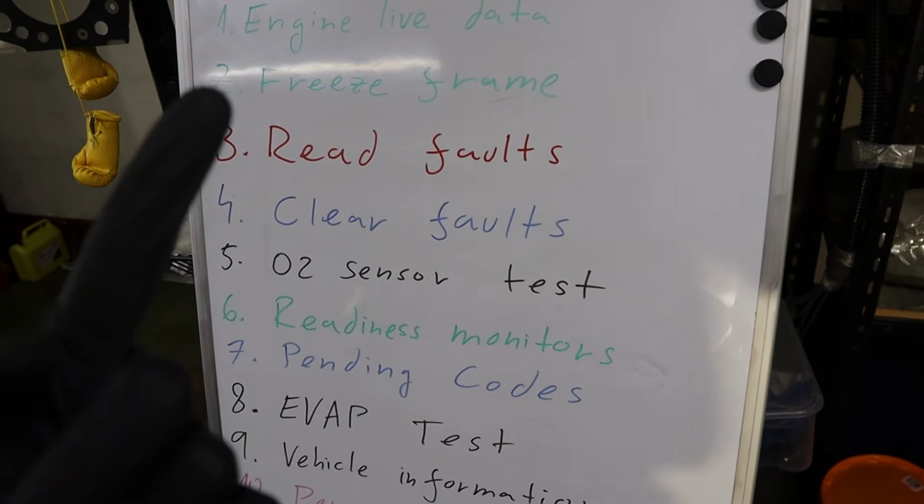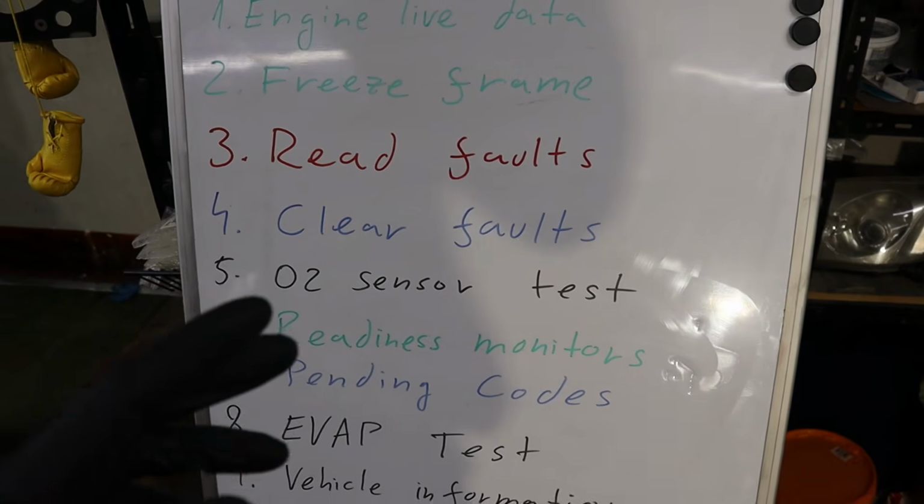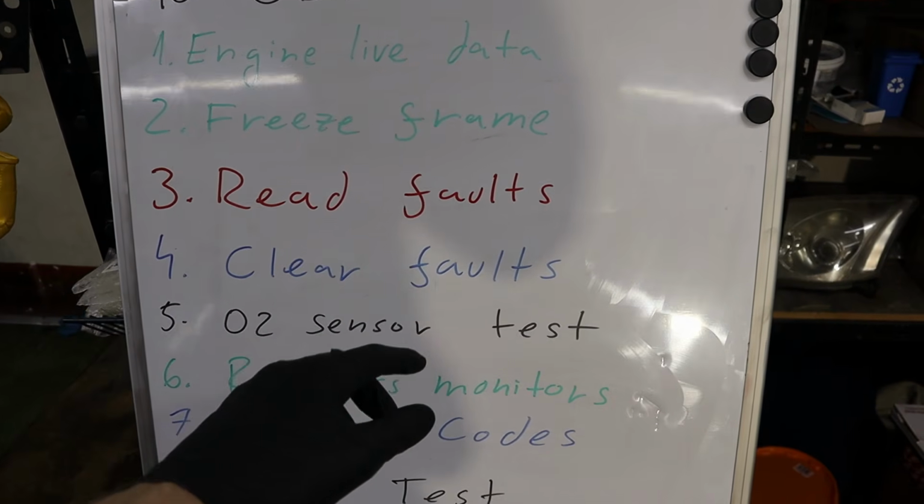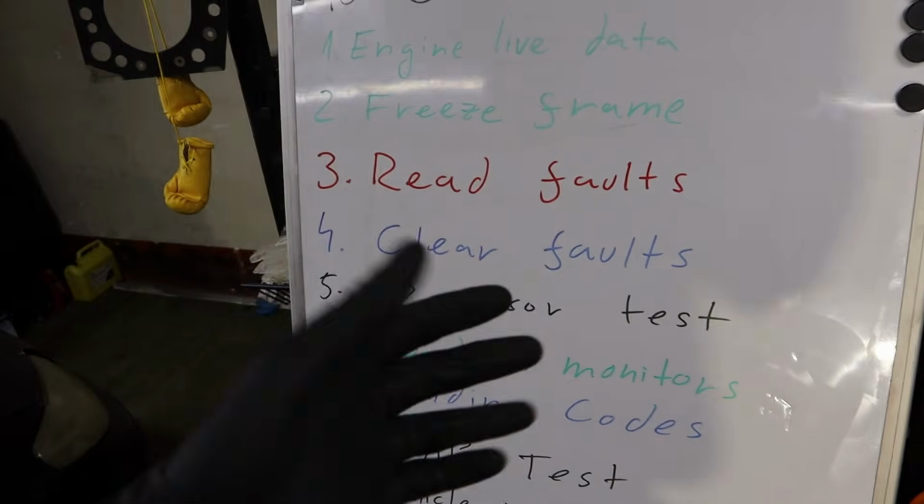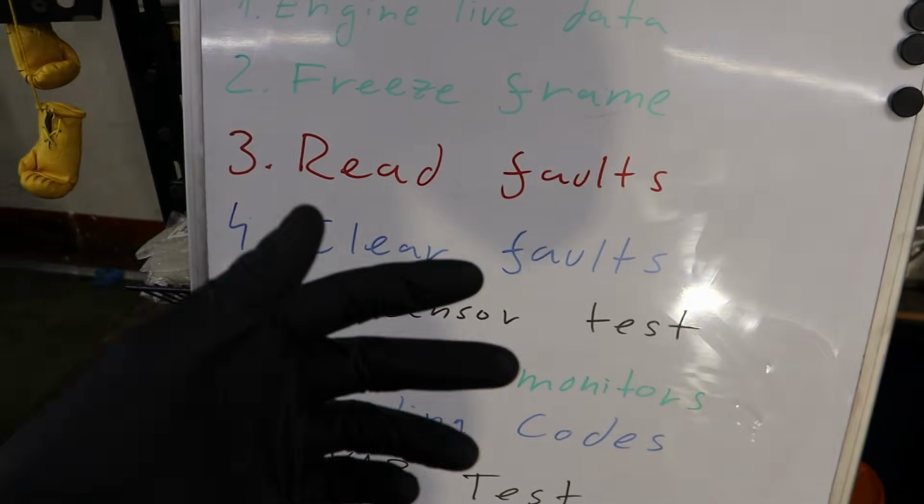If it's not passed, that could mean not that anything is wrong, but when you clear faults, most of your monitors will become incomplete, and you may have to drive your car for a day or two to have them completed again.